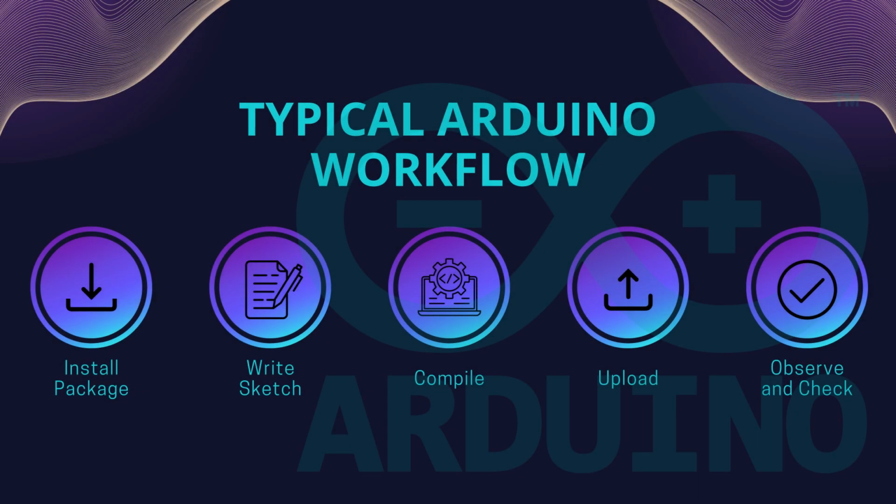Now, let's hop to the typical Arduino workflow. First, we need to select and install the necessary package for the board we will be using. It is followed by writing and creating the sketch on the Arduino IDE. Next step is we need to compile the sketch in order to check and verify the program. It is also a process where the sketch is converted into binary data so that the microcontroller will be able to understand it.